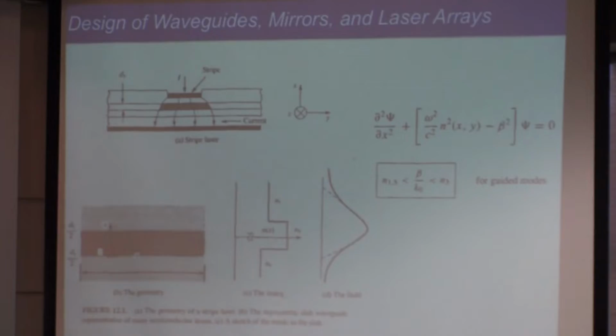But then you can shape, or you can direct the motion of these photons by playing with the refractive indices of the material. So in a semiconductor, typically what we are using is this active region, which is a thickness of d, which is that one here. That is a smaller bandgap material, so it has a higher refractive index. This is refractive index plot. Refractive index within this region is slightly higher than the larger bandgap regions here and here.